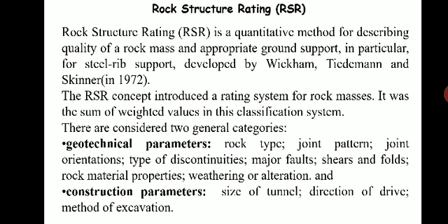So the RSR value of any tunnel section, how is it obtained? By summation of weighted numerical values which are determined for each parameter. The RSR concept is a very useful method for selecting the steel rib support for the rock tunnel, okay.